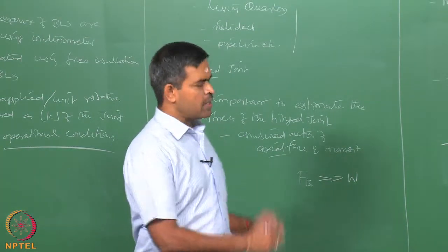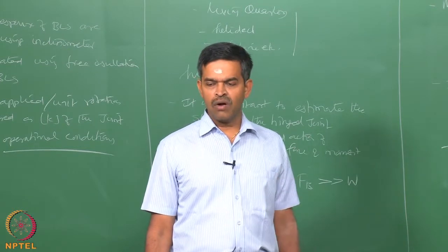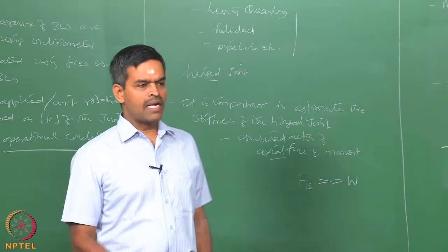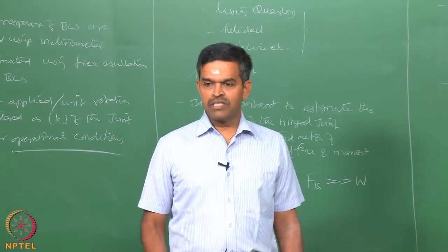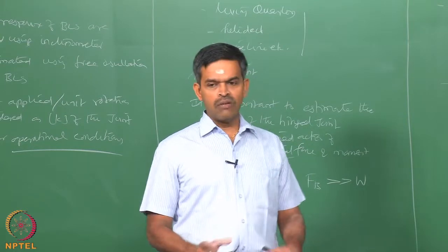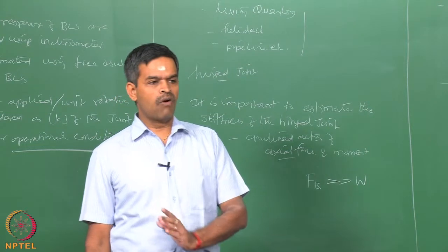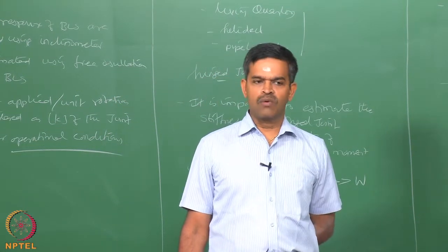The whole safety or reliability of a platform which is form dominated, like a Triceratops, depends on the failure of the hinged joint. Therefore, the characteristics of the hinged joint need to be estimated correctly, depending upon the actual behavior of the joint under the given loading system when the platform is commissioned for a specific ballast and specific draft in sea water.